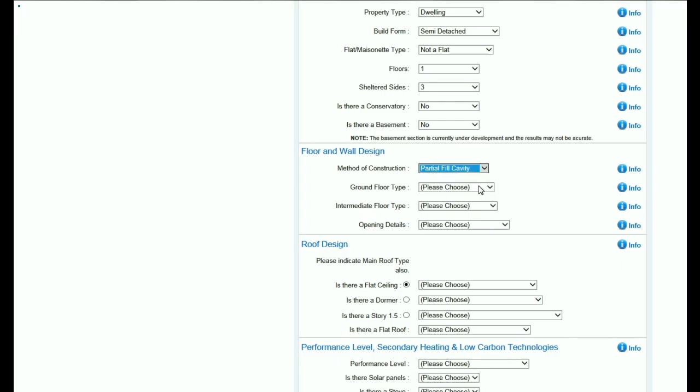Let's choose the partial fill method for this example. Insulation over the slab and timber joists. The user has the option of choosing the ACDs or model details to the openings. If the model details are chosen, then the performance is increased by 25% when compared to the default figure of 0.15 that is normally used in the BRE assessment. This reduces fabric construction costs by as much as £2,500 in a semi-detached dwelling.